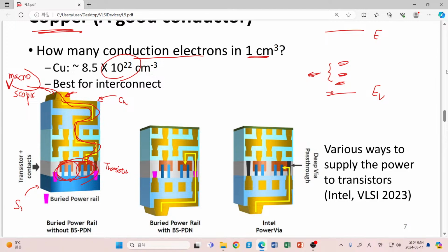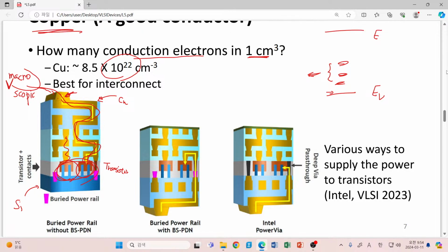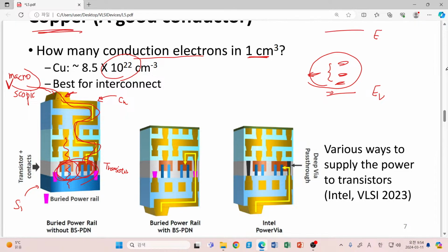Very nice. However, now think about a bad situation, where some copper material is moving inside our system and eventually enters the silicon material. Then what will happen? Once it is located inside the silicon, it can introduce some states located far away from EC and EV. So what will happen? We will see it later, but this is regarded as a very bad situation.